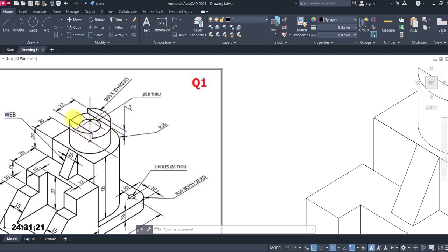So actually at this point, to get these two arcs, what I'm going to do is try and locate their center. Their center will be at a height of 15 from the base. The 15 is gotten from 20, the total height, minus this 5 depth cut.